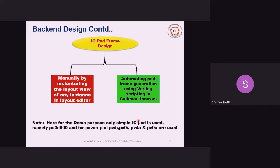And another way is automating pad frame generation using Verilog scripting in Cadence Innovus. So you can generate a Verilog netlist code, and you can run it in Cadence Innovus, and it will automatically generate the pad frame ring according to your desired specification. So this is one way. I will be showing this automatic pad frame generation using Verilog scripting in Cadence Innovus.